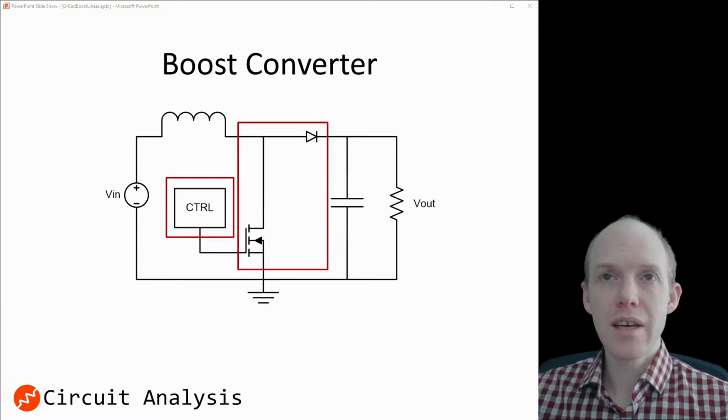To determine if the output of our linear block should be a voltage or a current, we look at the next component in the circuit. So since the next component here is a capacitor, we want the output of the linear block to be a current, because if it was a voltage, you would be essentially discounting this whole part. You'd just be fixing the voltage on here. But if the output is a current, then this is still an active part in our circuit, because we know that the output capacitor has a large effect on the Bode plot and the frequency response.